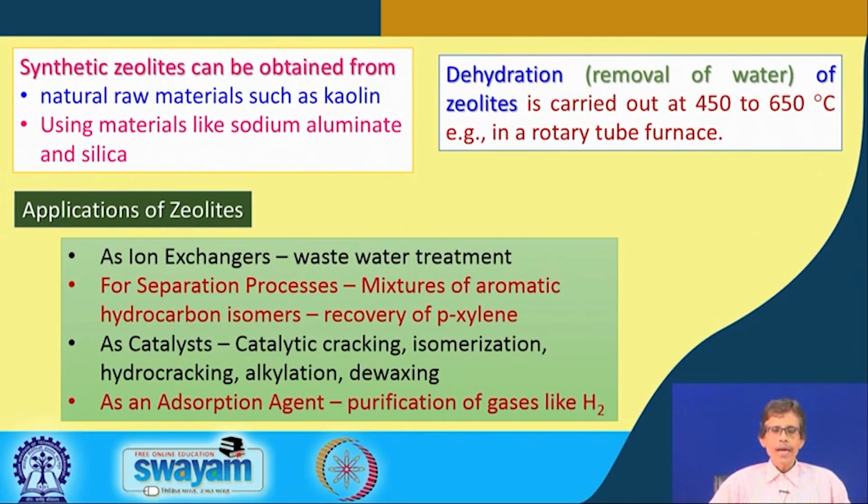So if we consider the other two varieties, that means the ortho form or the meta form, they can be retained within the zeolite framework, and only the paraxylene form can pass through that particular channel because of its shape and the size of those channels. Like in our filtration, we know that the small molecules or small particles will pass through the filter bed. It is also a filtering type of process, where the paraxylene will come out of that zeolite bed, retaining the ortho and meta isomers.